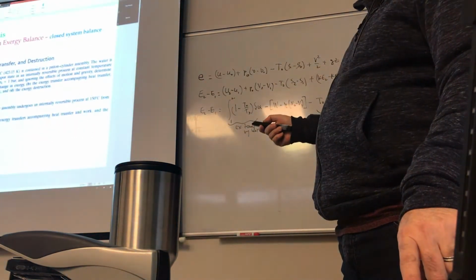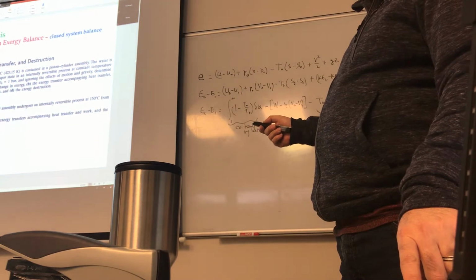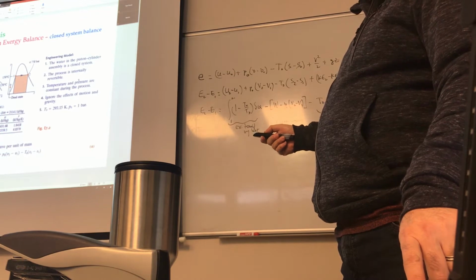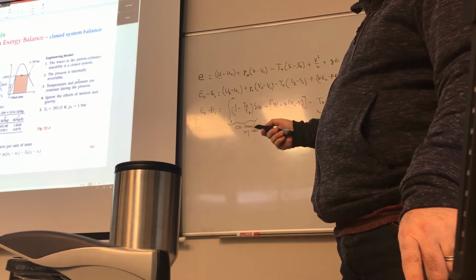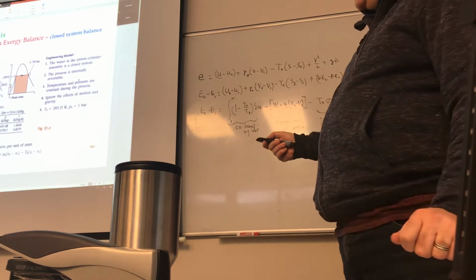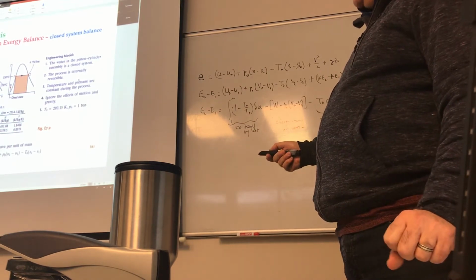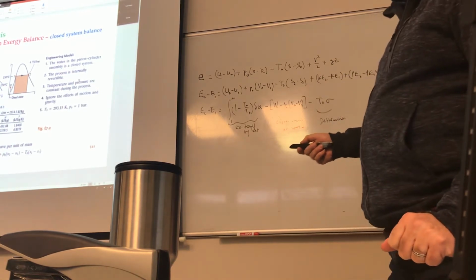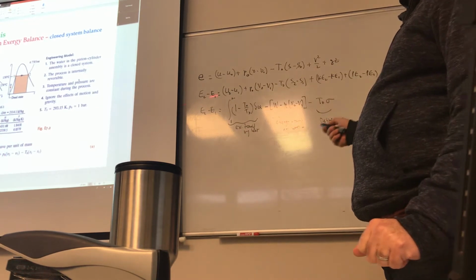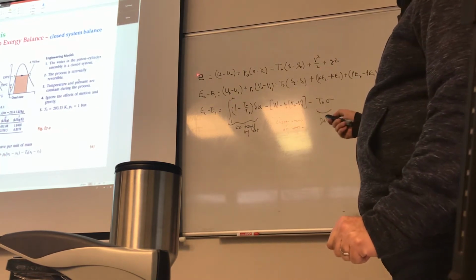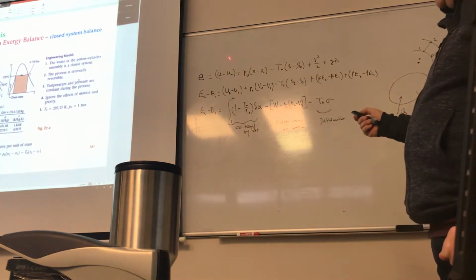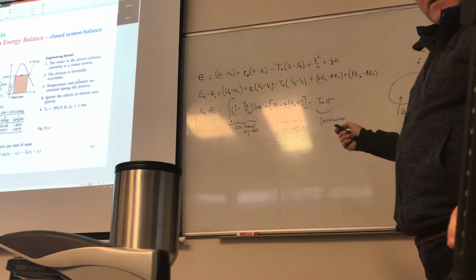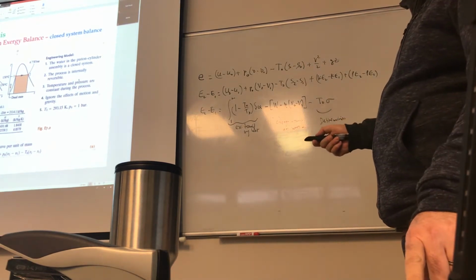All right, so we looked at this example also last week, exploring exergy change, transfer, and destruction by looking at the water that we're bringing in from saturated liquid to saturated vapor, right, across the system boundary. And from there, we're looking at what is the exergy change between the two states, between state 2 and state 1. When it's the case, this is the situation. This is the equation to always use. And obviously, all these values are simply read directly from the tables. Okay, so it's nothing out of the ordinary here.